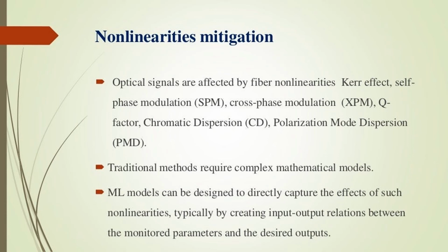Optical signals are affected by fiber nonlinearities: Kerr effect, self-phase modulation SPM, cross-phase modulation XPM, Q factor, chromatic dispersion CD, polarization mode dispersion PMD. Traditional methods require complex mathematical models.